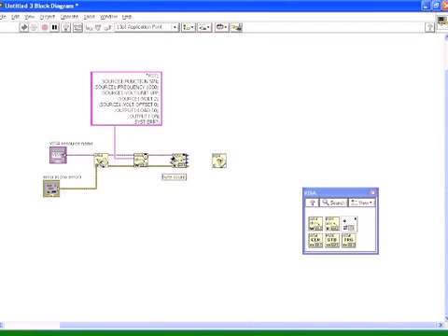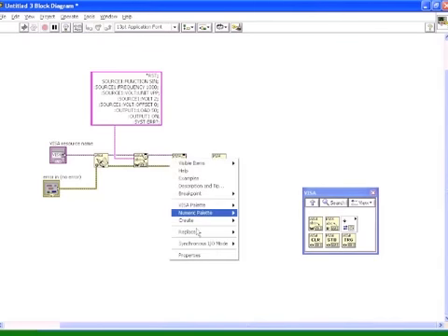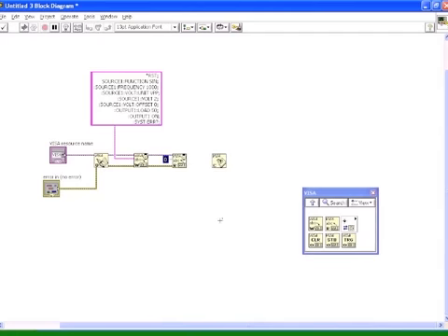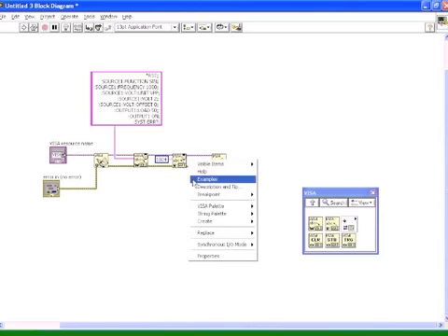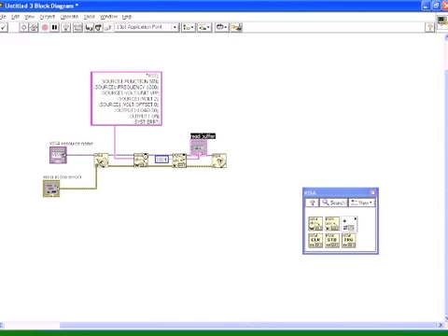Now with a read, you need to define a byte count for the data that's going to be returned. If you right click, go to Create, and I choose Constant, I'm going to enter 1024, then go ahead and do VISA resource out, do the error out. Now when you do a read, you're going to want to see the result. So on this read buffer, if you right click, go to Create, you want to create an indicator. I'm going to give it a new name of error.